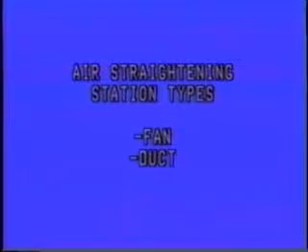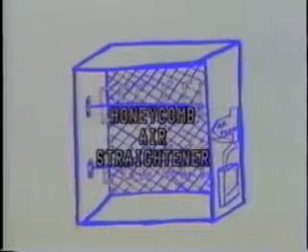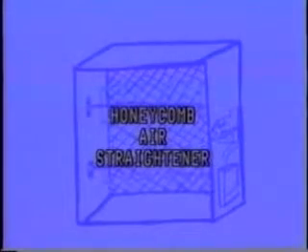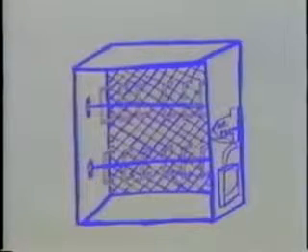The stations are generally broken down into two categories, fan and duct, the difference being the size of the honeycomb air straightening section. The fan models have smaller diameter honeycombs than duct models, providing better air straightening capabilities. It should again be mentioned that these devices must be installed at proper distances from the cause of turbulence, at least equal to or greater than that recommended by the manufacturer, or sensing accuracies will fall short of the plus or minus 2% accuracies claimed. A point often overlooked.